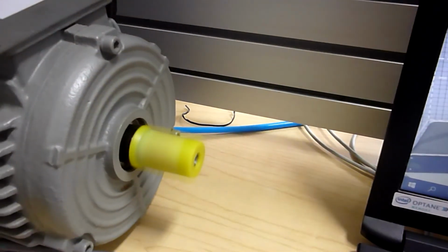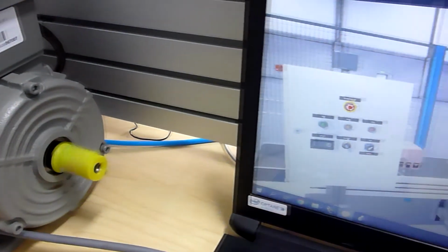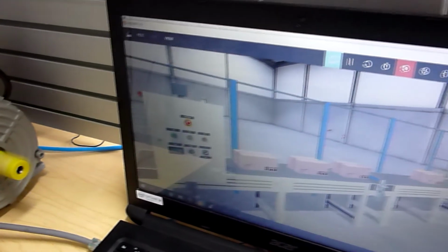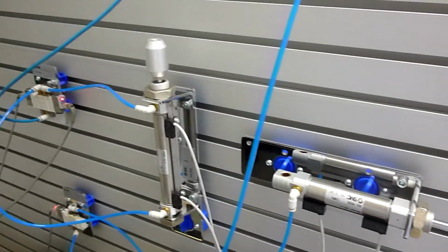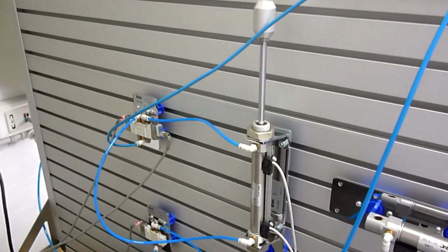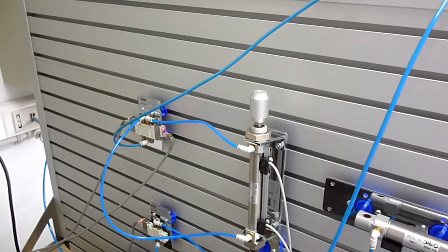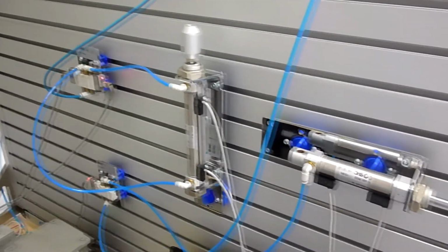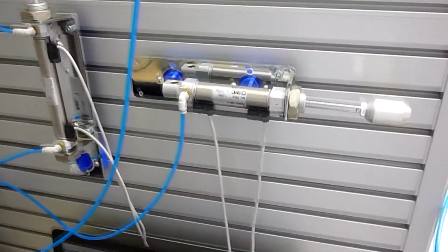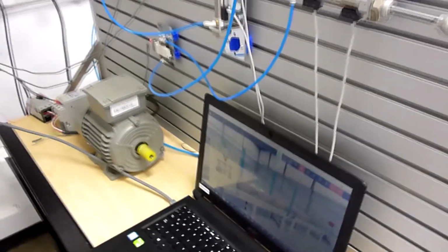As a result, we observe that the digital twin can serve as supervision in assembly and commissioning of control panels and physical machines, since it can operate the PLC without requiring connections to sensors or actuators. Also, there is the possibility of using the network protocol to use alternatives to the Factory I/O program, such as those offered by companies such as Siemens, Autodesk, Dassault, among others.